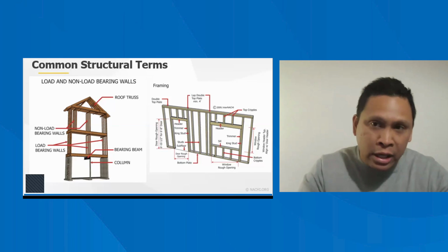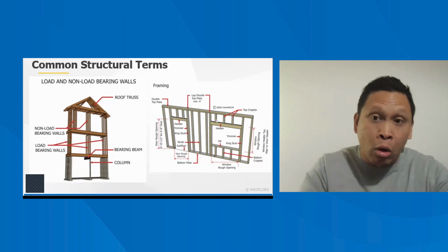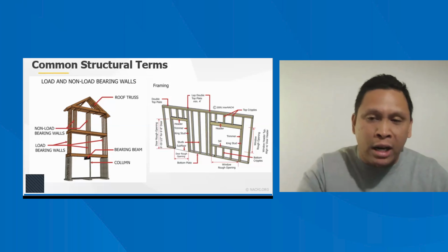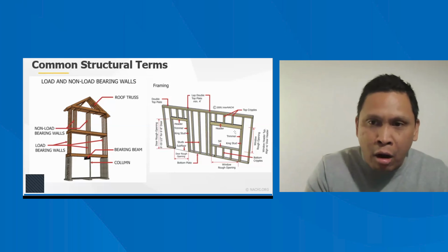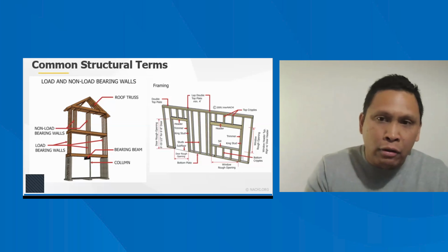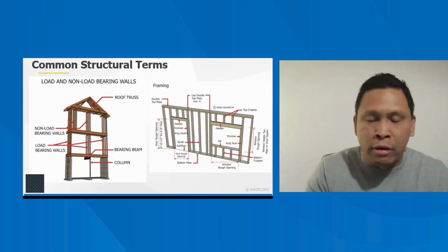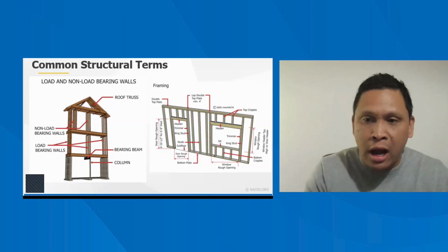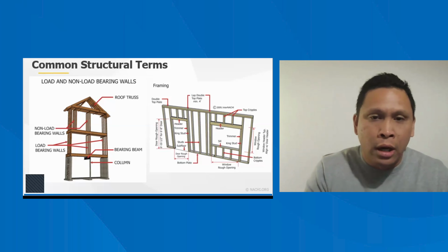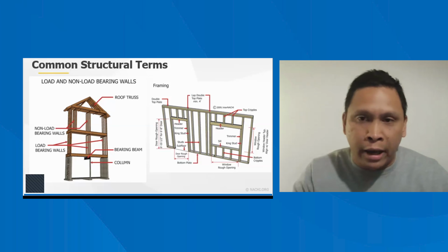We're actually directing the load around the window opening, creating that continuous load path around the opening. And then on the sides of the windows, you've got the shorter pieces of framing known as jack or trimmer studs. And then the longer pieces of framing, those are your king studs that are helping to transfer that load, create that continuous load path down into the next floor.